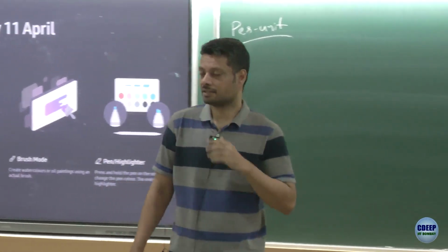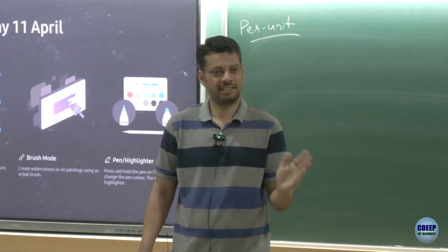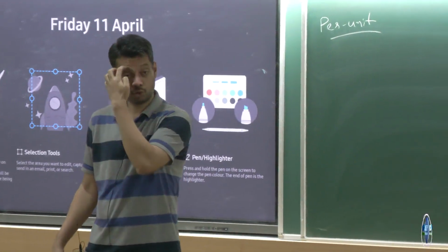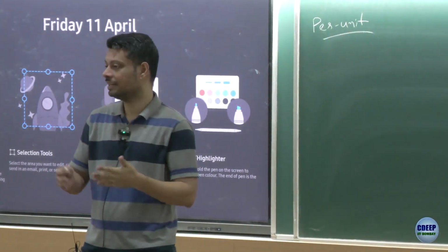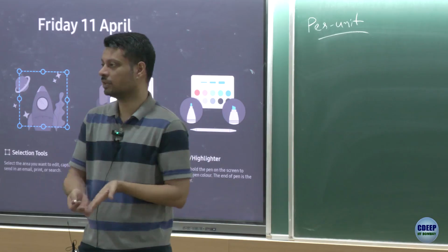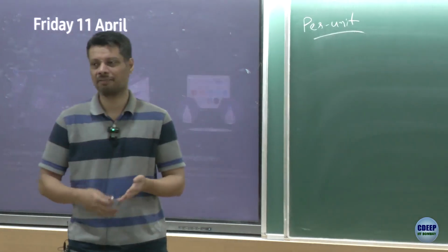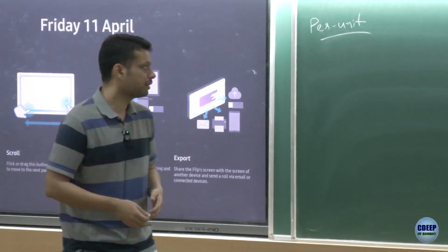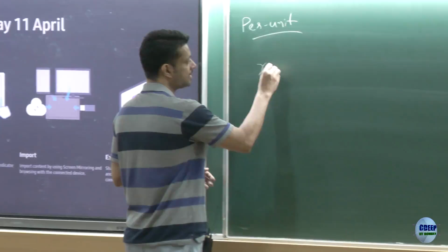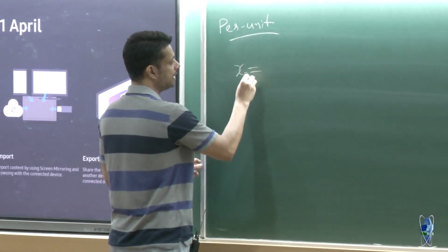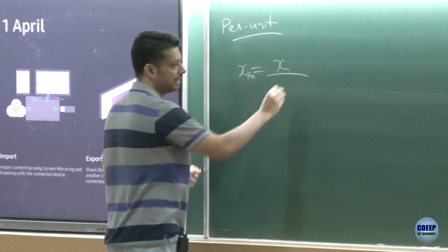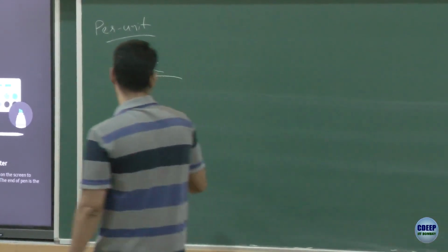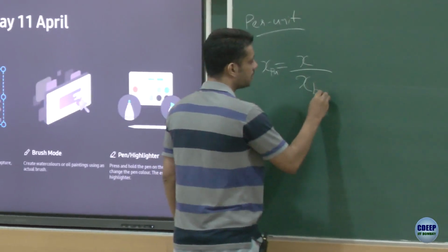So what happens is you have multiple voltage levels, right? 33 kV, 11 kV, and you can have different power levels also. So usually people can either express it directly in terms of the actual voltage, actual power, actual impedance, or a simpler way is to represent all of these parameters in terms of per unit. Any quantity x in per unit is given by x upon x base.